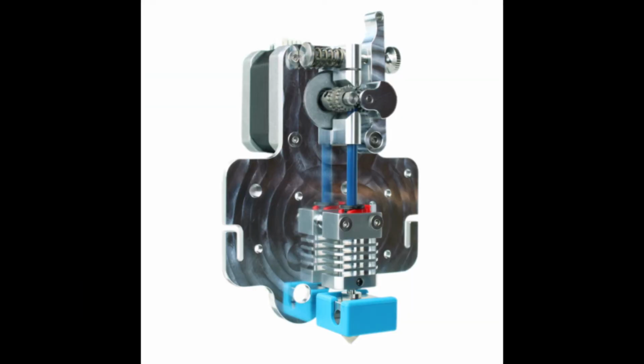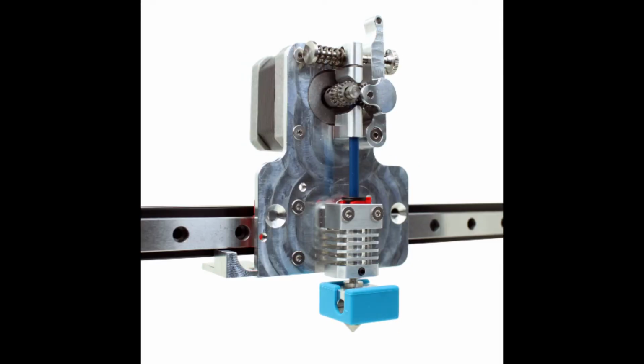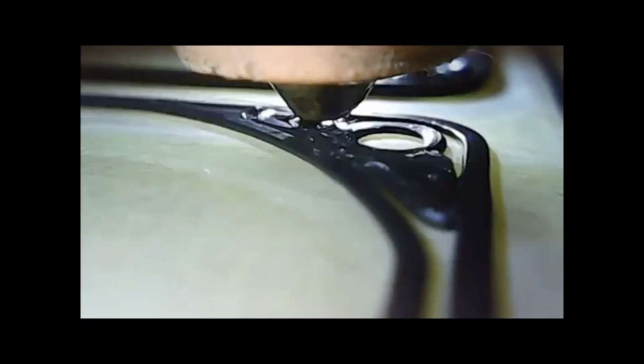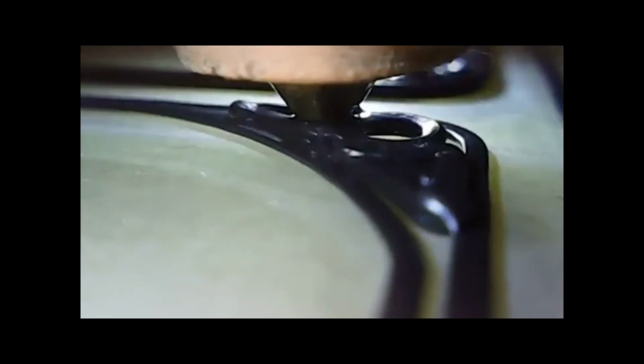After I was done with that, the next few upgrades I did were from Microswiss, specifically the direct drive extruder and the all metal hot end. The direct drive extruder moves the extruder stepper motor away from the edge of the 3D printer and onto the very top of the tool head. This allows the 3D printer to 3D print much more flexible materials while also reducing stringing. Of course, the added weight also has to be accounted for, which I'll explain in a minute. The all metal hot end allows the material to be melted at a higher temperature, as well as being able to be melted at a quicker rate.